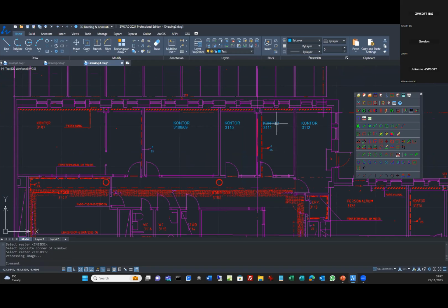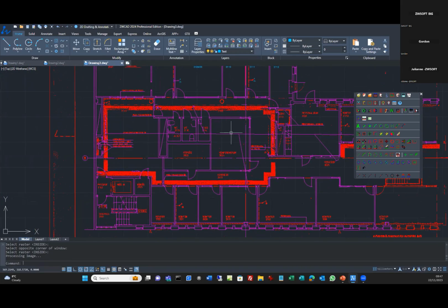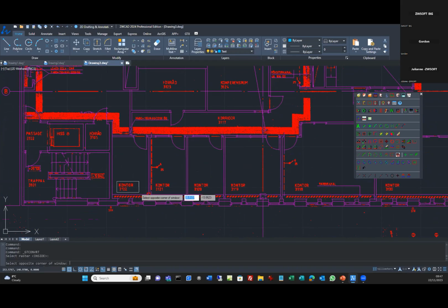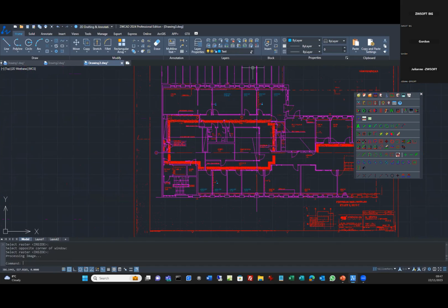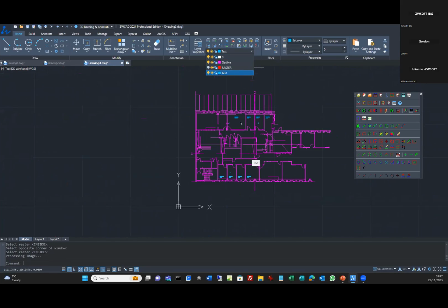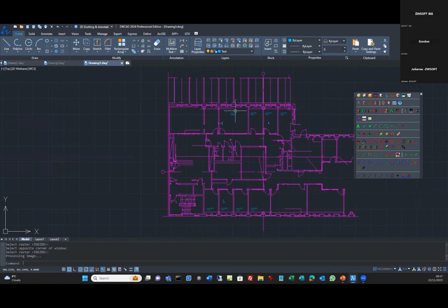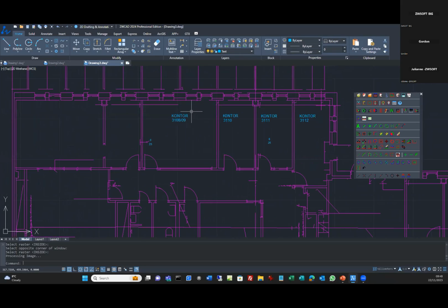Because it knows what the characters are and the text is, then I can go around more of the drawing. And because it's the same text, it's same characters, then I can just keep on selecting the different bits of text that I want to convert, and then you have your drawing. So within a couple of minutes, I've now got a DWG file that contains proper text and lines, circles and arcs. So I've got all of my building layout and also my text that I want to use. So it's a very, very quick way to manipulate and change and convert your data.